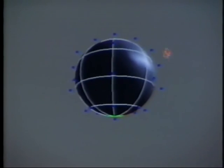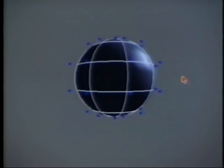A single surface object that forms a sphere will always have poles on both ends because the sphere is still a rectangular grid in structure. Only two things have happened to it. First, it's been closed in the U direction, and second, it's been capped in the V direction.